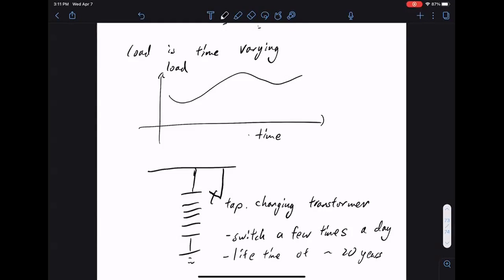But do you see any challenges with this methodology once we have, say, a lot of solar or a lot of storage or a lot of electric vehicles? Let's say you have a lot of solar. What does the load look like? Now it's very smooth changing. If you have a lot of solar, what does the load look like? Right, it's unpredictable. It also varies a lot.